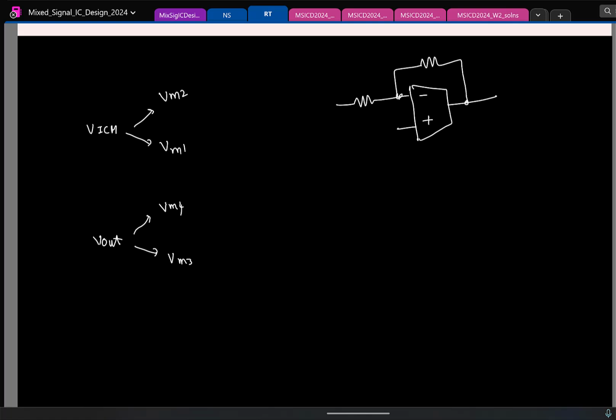So first of all, should this be connected to ground? Remember, this is going to the gates of the differential amplifier. Should this be connected to ground or something else? If I connect it to ground, what will happen? Yeah, there will be no biasing. So this should be connected to some bias voltage. Let us say that is some VB2. Similarly, at the input side, let us say I use some VB1. On top of it, I apply small signal Vi, and let us say R1, R2.